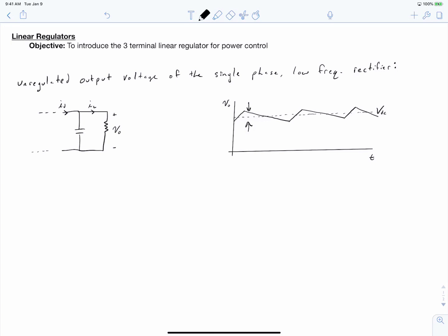When you want to design a DC voltage supply, you have to be sure to pay attention to the design spec for the system that you're driving. So if you're trying to drive a microcontroller, you can pull up the datasheet and figure out how much ripple voltage is allowable on the voltage rail. For most real loads, we want to have a regulated DC voltage. And we're going to spend a lot of time in this class talking about ways to convert one DC voltage to another DC voltage efficiently and in a compact form factor.